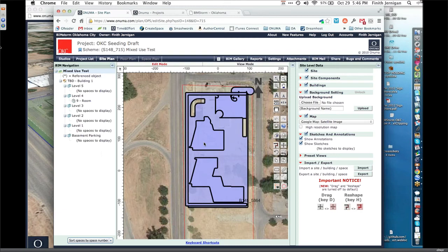Amber, do you know enough about this to tell them how to make this go away, or are they stuck with this? They just have to set up the model as far as it's one slab per level as you're working in Revit.